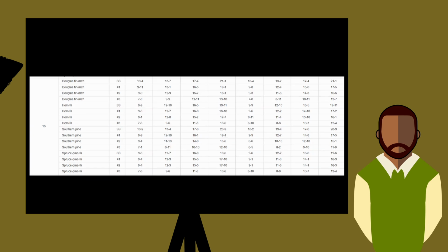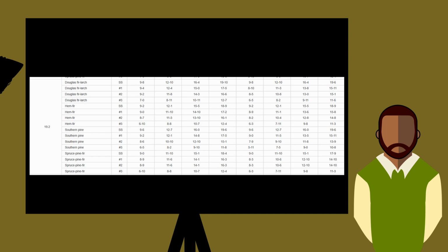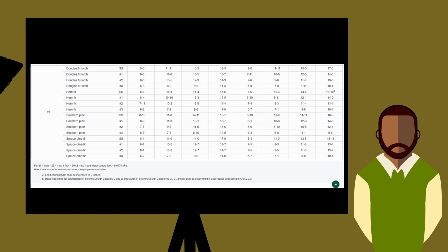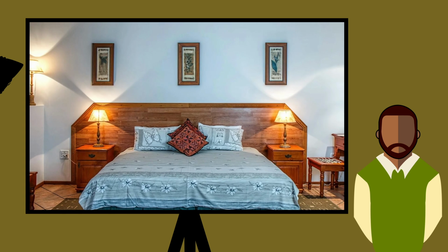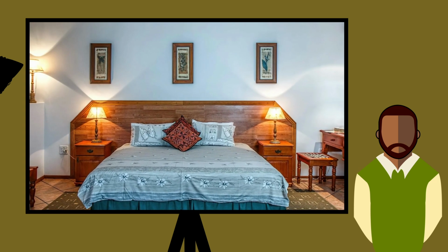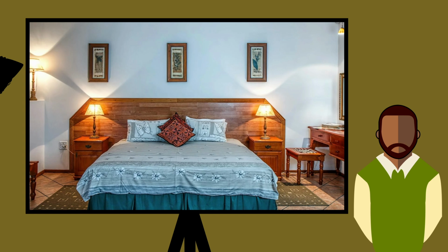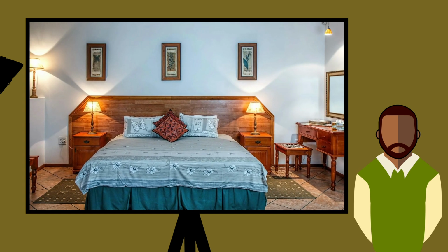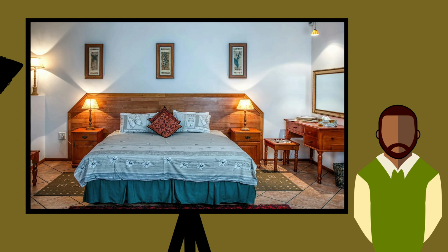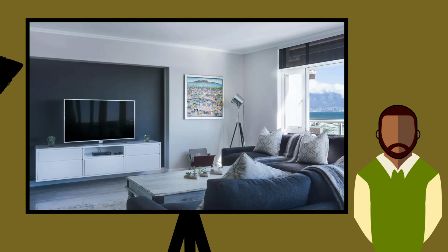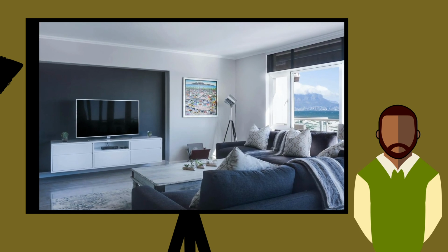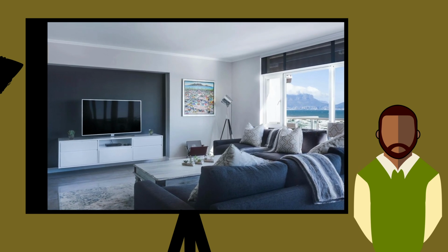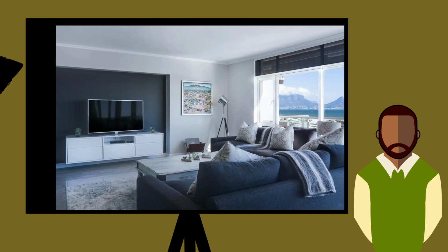When it comes down to these blocks, what's happening with those? Usually 30 pounds per square foot we put as those are sleeping rooms. So this is where usually the idea is one person is using this room as their personal space to sleep. They come in the room and there's not going to be a significant amount of foot traffic. When it comes down to hallways, living rooms, kitchens, that's where we stop using this concept of 30 pounds per square foot, and that's where they want to make sure and beef up the floors.